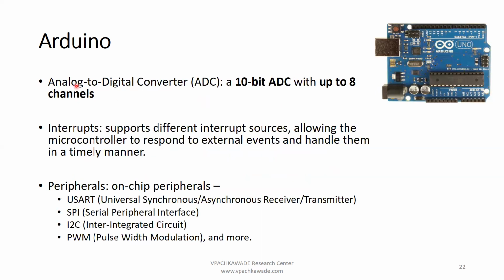Before that, this Arduino board or microcontroller also has an inbuilt A to D converter, which will perform analog to digital operation. The capacity of that A to D converter is 10-bit, so it has a 10-bit resolution. Look at this section named analog in.